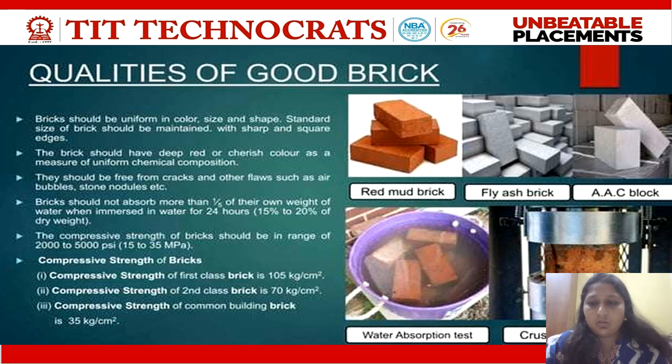Now let us discuss the qualities of a good brick or the properties of brick, and how we are going to check them. The very first one is that the brick should be of proper shape, proper deep red or cherry color. All its edges should be sharp enough. There should be no breaking or coming out of particles. There should be no white spots or any type of spots on it. There should be no flaws in it. When we immerse the brick in water for 24 hours, it should not absorb water more than 1/5 of its own weight. The compressive strength of brick is generally 15 to 35 megapascal.